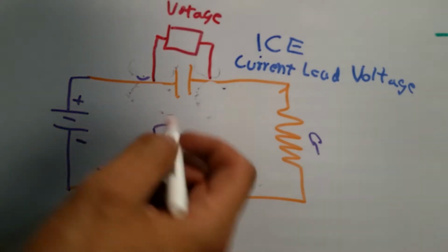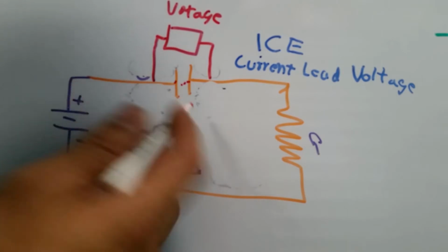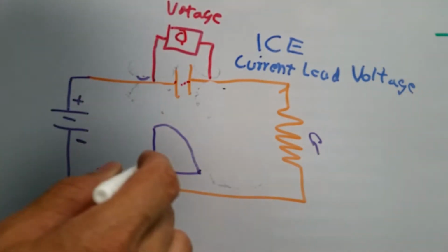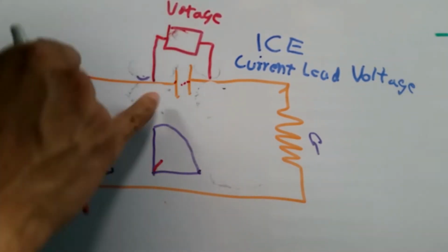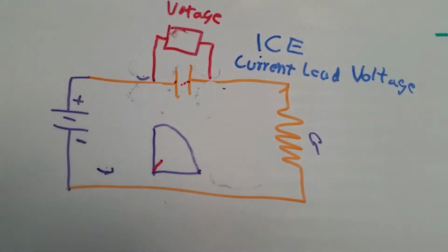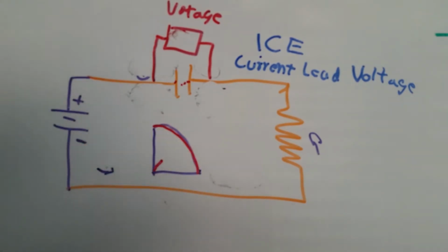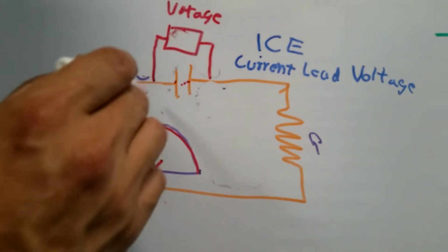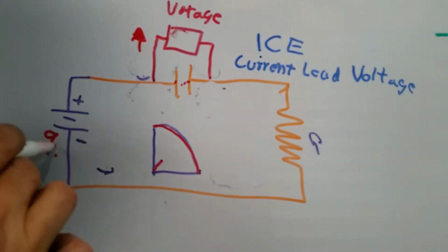As current is flowing, the capacitor in essence kind of looks like a short, because it seems like electrons are going through it. So the voltage starts at 0. But as the capacitor starts charging, it starts accepting fewer and fewer electrons, which means current flow is going low, like I indicated a moment ago. As that happens, the voltage across the capacitor starts increasing until it finally reaches the full potential of the battery.